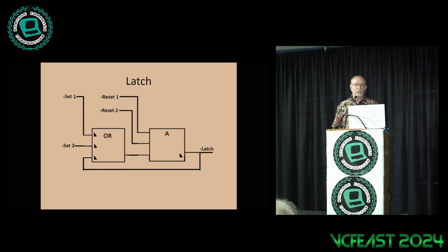Now here's one of my favorites. It took me a while to wrap my head around this. This is how they implement a latch. They don't use a flip-flop because that's expensive, too many transistors and diodes. And back in this day, every diode and transistor cost money to IBM. So they really worked hard to cut it back. As we saw before, both of those gates are NANDs, but they chose to draw them 2 different ways, as an OR and an AND, just to logically think about the fact the first one is setting and the second one is resetting signals.